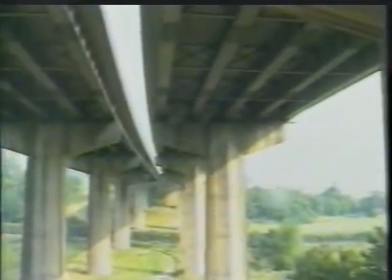It is important to remember that, with a continuous beam supporting a floor slab or bridge deck, the slab will provide restraint in that region of the beam which is subject to a sagging moment. But, adjacent to the reactions, there will be regions subjected to hogging moments, where the lower flange is in compression, and bracing of this flange, too, may be necessary.